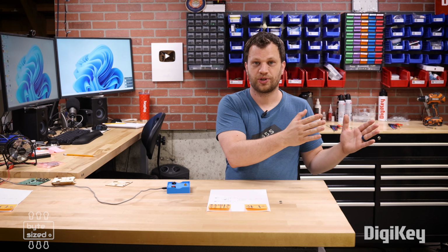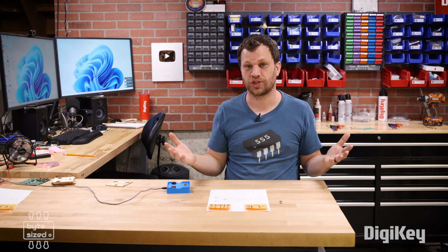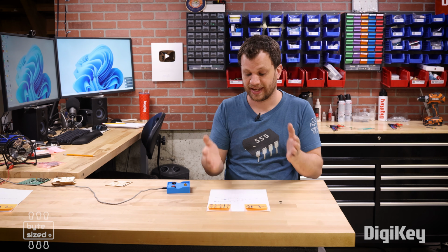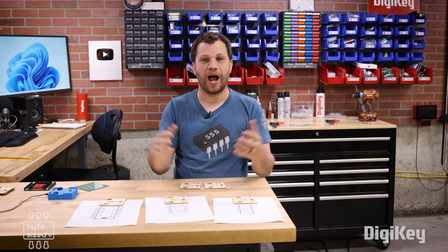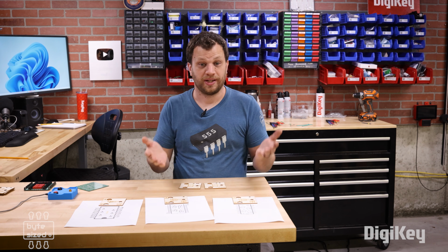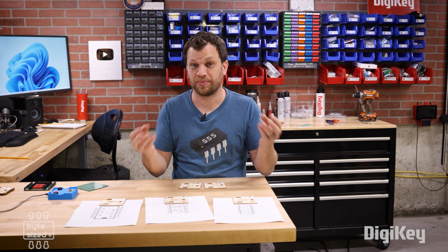Let's take this off so that it's not beeping and summarize what we've learned so far. We can use transistors to build logic gates. Logic gates are what allow electronics to make decisions. Then we can combine logic gates into flip-flops, which store memory. On a basic scale, this is how computers make decisions and remember things. So how would you practically use these? Well, the easiest way is to get an integrated circuit chip like these that DigiKey sells that has logic gates and flip-flops built into it.